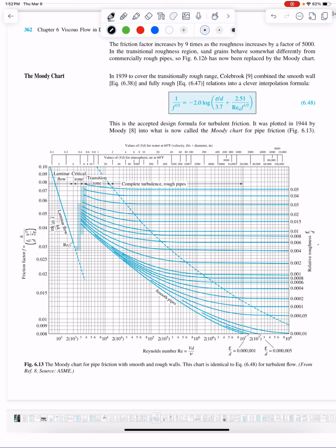So as you see, these two roles, your pipe characteristics and your flow characteristics, play a role in determining what the friction factor is. Did I make that clear over this chart? Once again, friction is dependent on these two terms, Reynolds number and relative roughness. In this problem, we don't know what the velocity is. That's what we're trying to solve for. We want to know what the flow in the pipe is, and without knowing the speed, we don't know the Reynolds number. So we cannot fix the x-axis.